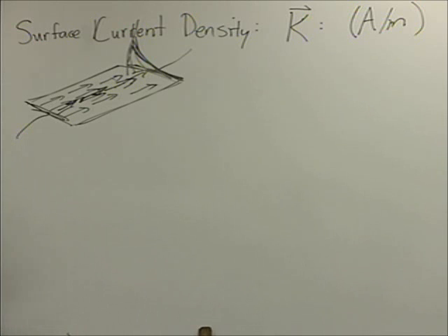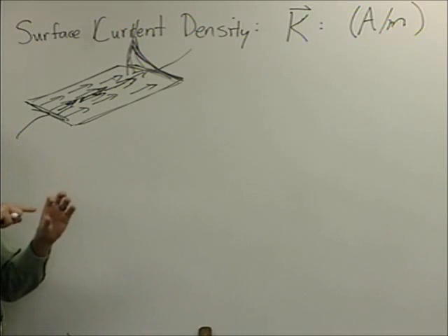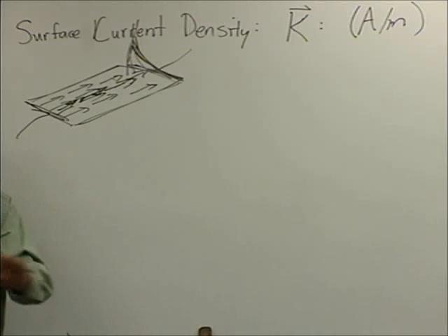Now, what they are often used for is in conjunction with a current transformer ring, which is an iron thing that you clamp around a wire. You can get a pretty good estimate of what the current is going through a wire. That has to do with Ampere's law. We haven't gotten to that yet. So good anticipation of the thing that we're going to cover.